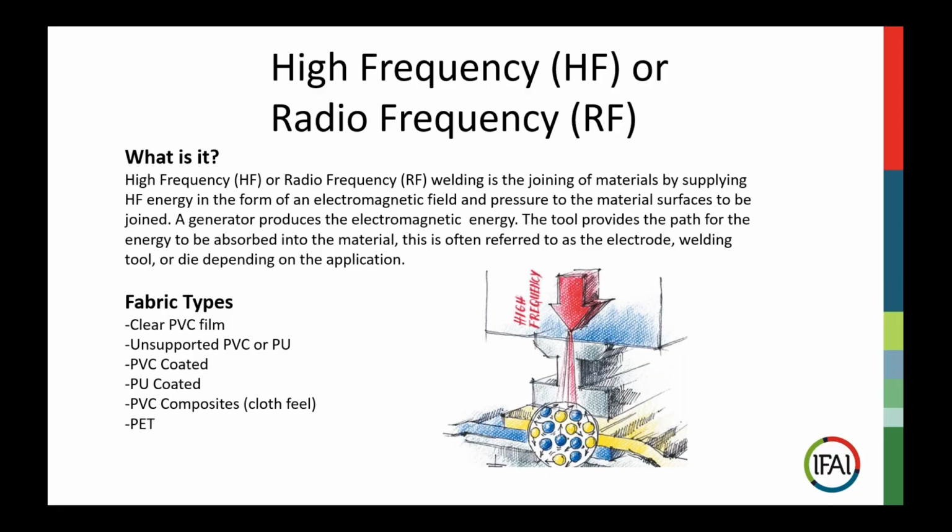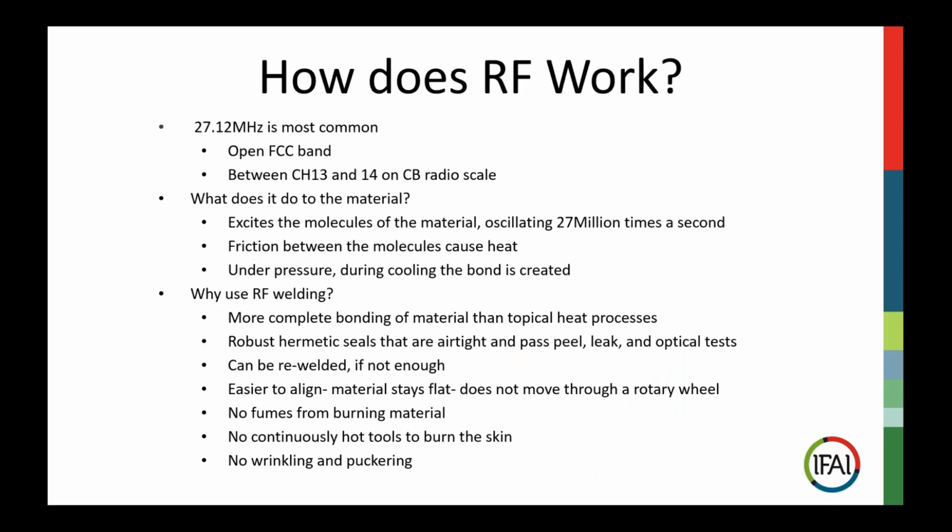Here you see a list of materials that are naturally reactive to RF or HF, and you'll see that I actually did include a PVC composite, which refers to new materials now. There's new technical materials coming out every day, and some, like the Natura from Herculite, are actually very cloth-like in the touch and the hand, and they're used in place of an acrylic, for example. They are completely RF weldable, so don't be fooled that you have to see some kind of shiny material to do RF welding.